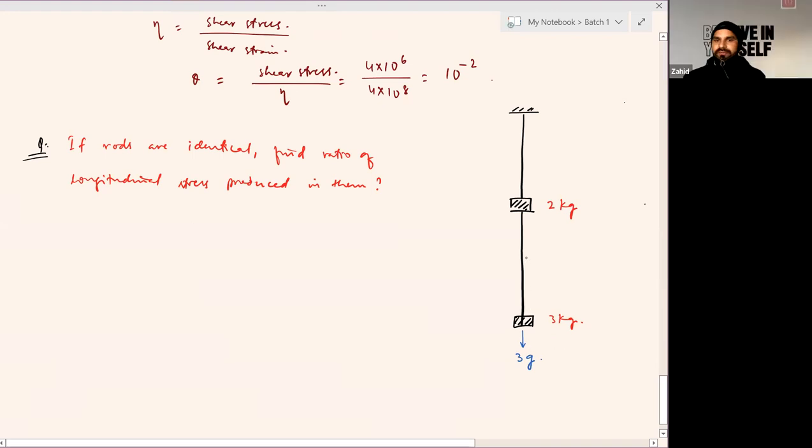Now, if a wire or rope gets straightened due to applying some force to it, there will be some tension developed in it. So it must act opposite to this point of contact. Let's say this is T1. Will this particular block move downward or upward?